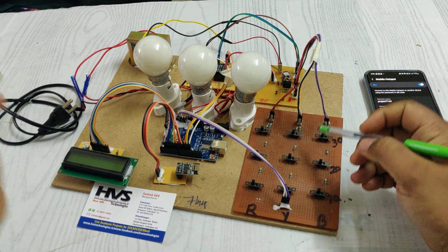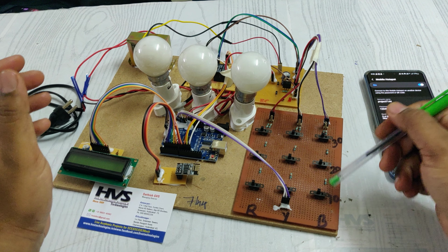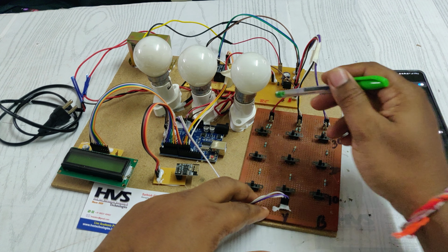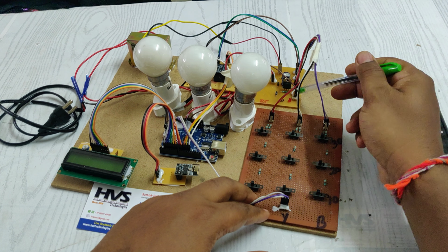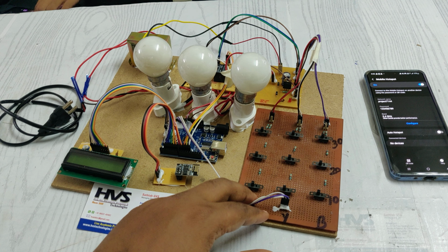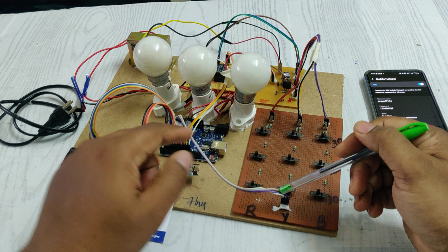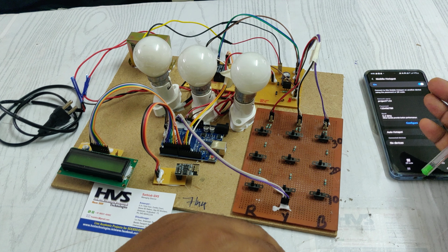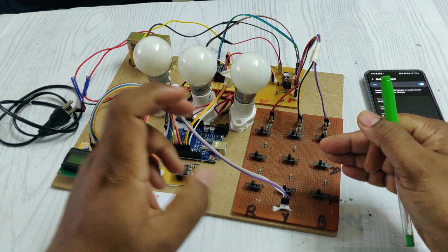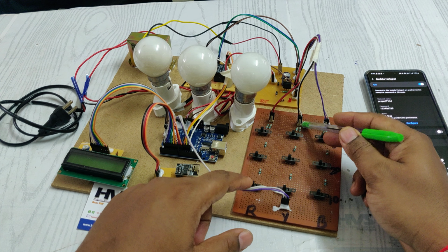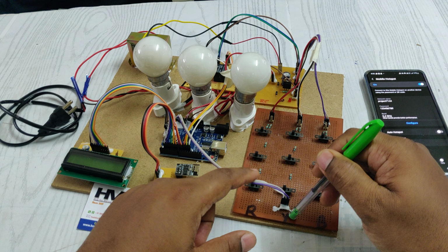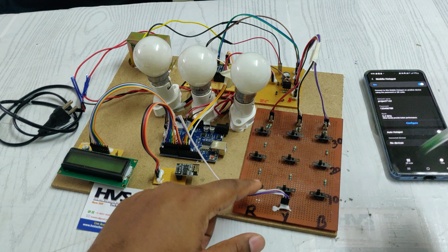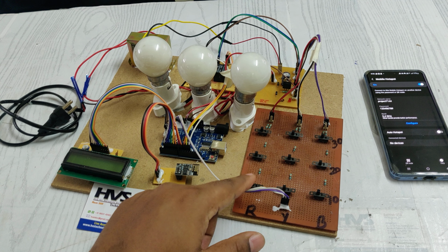Same for the remaining 2 phases, R, Y, B. The power is transmitting from this section, sorry, this is the transmitter section, from this main distribution, and from there this is the receiving section. There the Arduino is placed to measure the voltage. In real time we would measure 230 volts, but for demonstration purposes we are using 5 volts transmission at this section and receiving 5 volts at the microcontroller, this Arduino Uno board. Whenever the voltage drops, that is based on the resistance, nothing but the length of the wire.